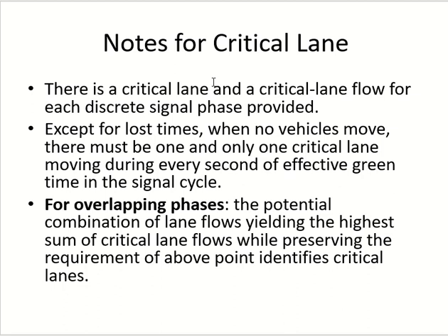Okay, so this is how you decide which overlapping option is more beneficial. You have to look at the summation of critical lane volumes from all phases. You add them together and you see which one gives you a higher sum. Clear? Any questions? Okay, thank you.